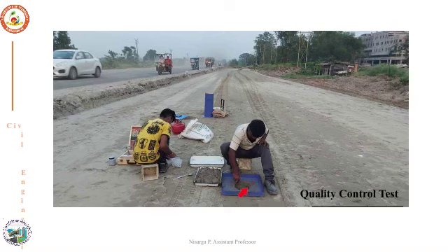At the frequent intervals, as we mentioned earlier, if you are doing it for the embankment, for every 500 square meters of the compacted area we need to take one measurement, and if it is for the subgrade, for every 1000 square meters of area we have to take one measurement. We have to take at least 5 to 10 sample measurements, and the mean value of it represents the field density obtained.